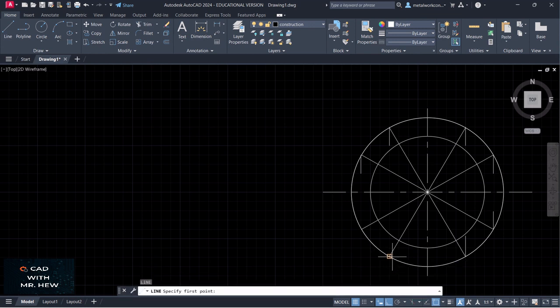So we're going to go line there. We need to turn off object snap because, see this little hourglass looking thing, the line is going to go to the circle. So we're going to turn off object snap and go up, and then we turn it on when we finish with the line, right? So we turn it on to pick up the intersection here, right? So we go line, here it is, and we go up, enter.